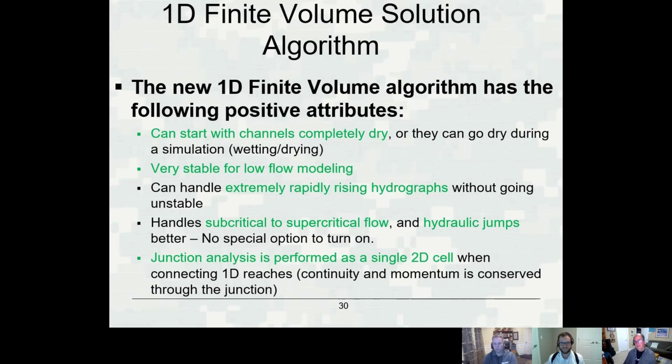So yeah. Oh yeah, I've been looking forward to this for a long time because I just think back to the amount of time I've spent troubleshooting models for this very reason, and trying to use the tricks and tools to keep it wet or to keep it stable when it's really low flow. And the fact that you can't directly model, say, a flash flood, where it is starting out dry and you literally have this wave of water that just moves through. And Gary knows all about the Missoula flood model I built years ago in 1D, and that was very tricky to get started. Much easier in 2D for this very reason.